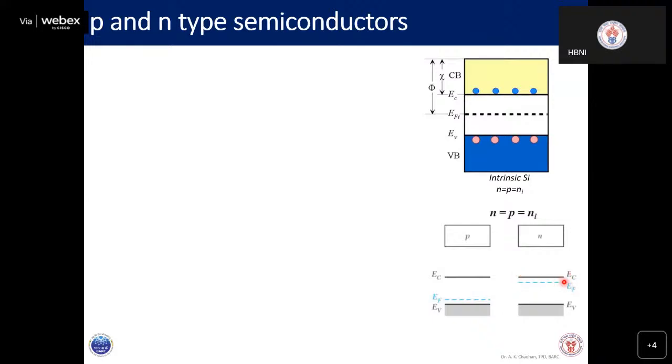The Fermi level in N type material is close to the conduction band, and on the other hand, the Fermi level in P type materials, where holes are used, is very close to the valence band. You should know this very clearly, because when we make junction devices, the role of this Fermi level and its alignment becomes important.